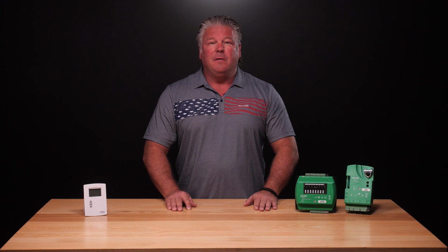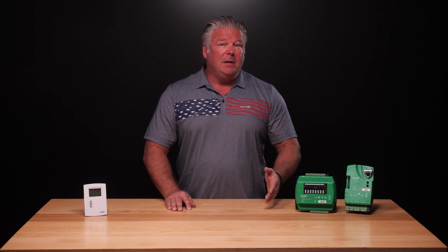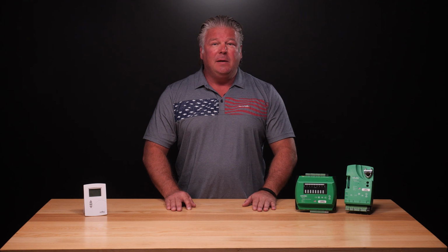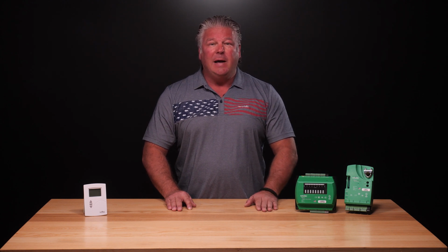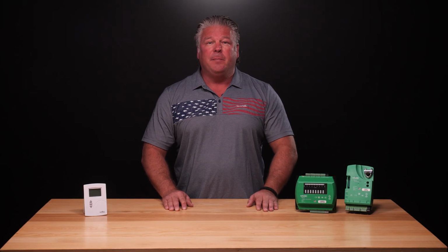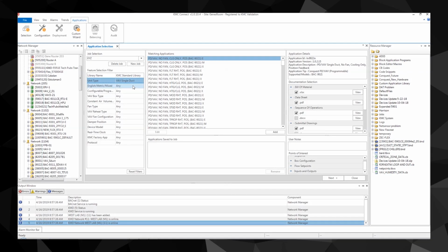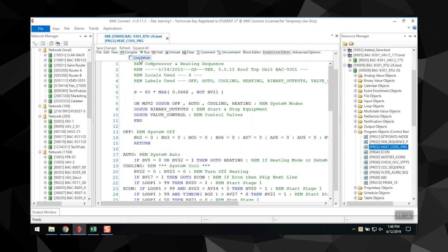For example, if the fire safety has been triggered, the damper then closes. If the room is not occupied and the temperature is below the unoccupied heating set point, then the room heating begins to warm. If the CO2 level is too high, then outside air is brought in. All DDC manufacturers allow technicians to specify desired set points for the controllers. Most vendors have incorporated pre-written programs into their controllers that cannot be changed, but some manufacturers, such as KMC Controls, allow more flexible ability by providing a way for technicians to easily modify pre-canned programs.